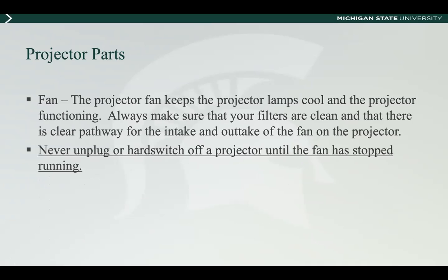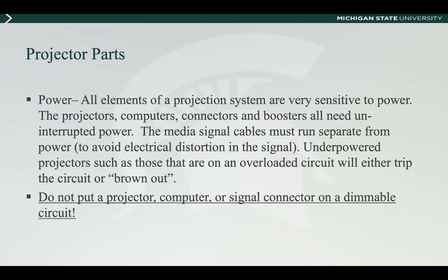So never unplug or hard switch off a projector until the fan has stopped running completely, right? You've noticed this before too, if your teacher's ever turned off the projector but it seems like it's still running. That's just the fan still running, because even though the lamps are off, there's still heat within the projector. The fan is running to cool down the projector, because if you turn off a projector before the fans are off, it'll just sit in that heat and melt things, and that's just not good. So the fan's a really important part of a projector.